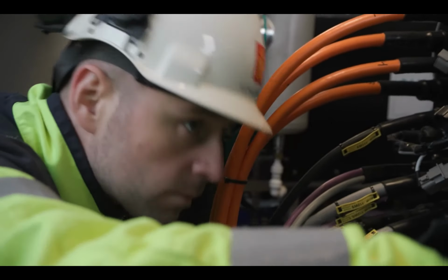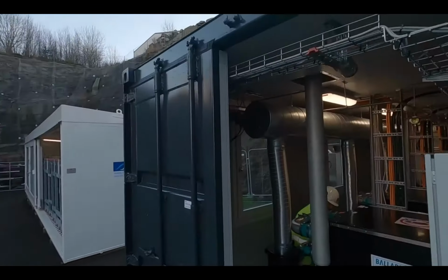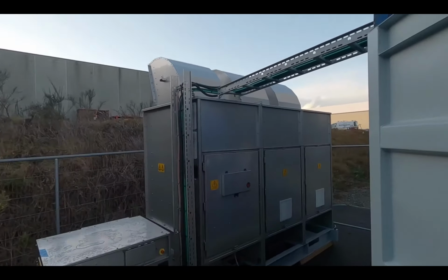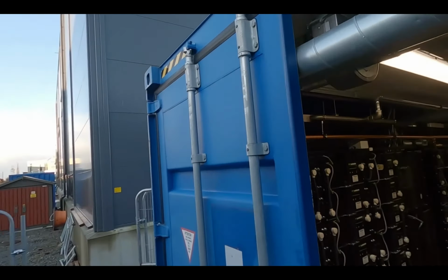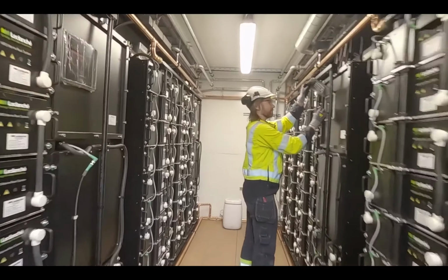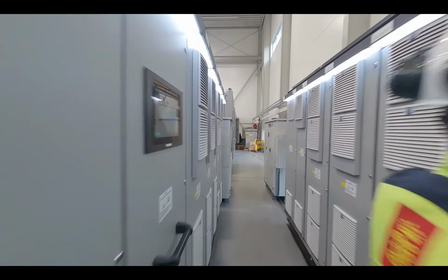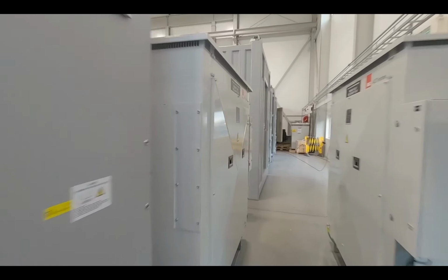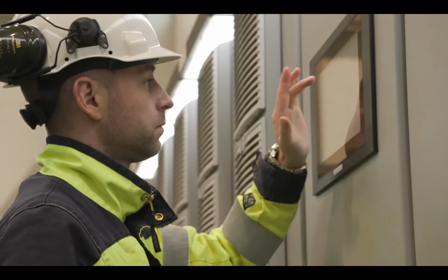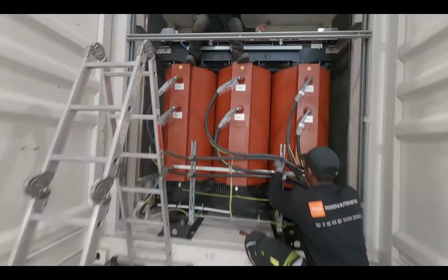And the process is remarkable. The fuel cells are installed in 2 containers. Inside each container, the fuel cells convert hydrogen to electric power. Batteries provided by the fuel cells provide extra power while the vessel maneuvers to and from port. Multi-drives manage and control the energy transfer from the fuel cells and batteries to propellers and main accommodation of the vessel. Switchboards connect energy sources with other areas needing to draw on them.